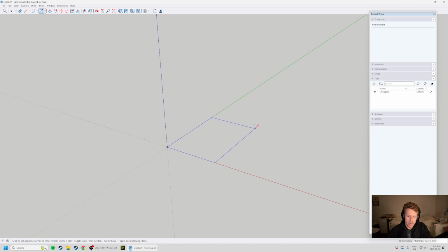So one thing is, unlike Revit, I find this part is a little bit clunky, but keep an eye on the bottom right here. If we want to instruct SketchUp to create this rectangle, we can actually type in the first number and the second number. We can eyeball it, but I would recommend you type these numbers. You can see here I've got 5,000 millimeters by 10,000 millimeters or so, but those are pretty loose. You see 4872 by 10,389.